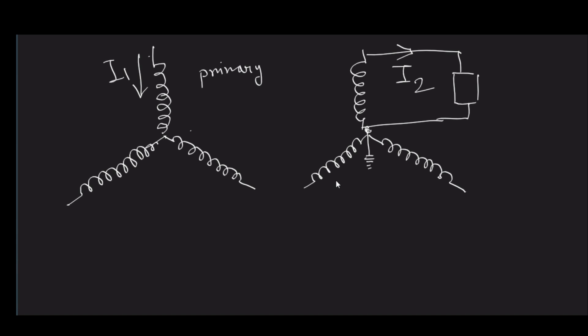But when you connect it, what would happen? There is no neutral, so when current flows, it will cause a flow of current through these two branches. However, there is no corresponding load present in the branch. So when this current flows through this branch, it will cause an imbalance in the voltage induced in these two branches, right? So that is a problematic issue.